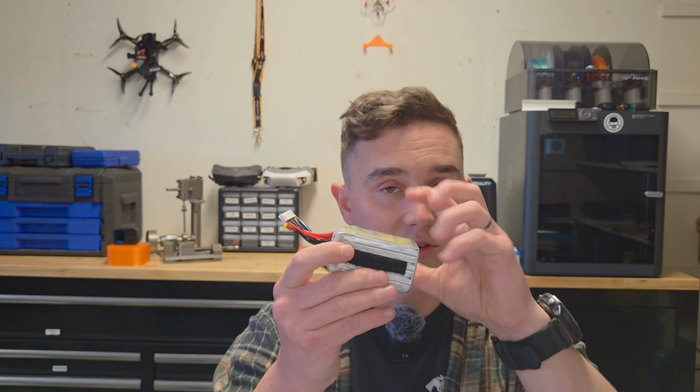So safe charging. Okay, it's always safe to charge at 1C, which means if I have a 1400 milliamp hour battery, I can charge it at 1.4 amps. I charge at 2C personally, which means I charge this battery at 2.8 amps. Whenever you're charging, especially when you're charging a lot of batteries, always be in the area. Okay, look up a video of unsafe charging or LiPo explosion or something like that, and you'll see that this expands. You hear it starts fizzing, and then it bursts into flames. Not great in your garage. Nobody likes a house fire.